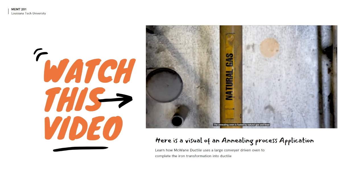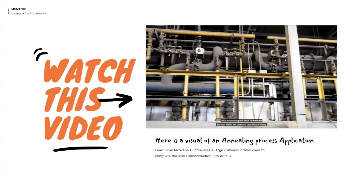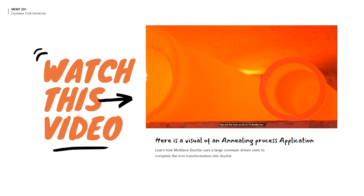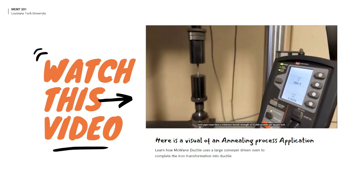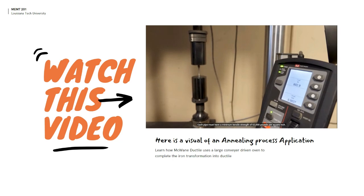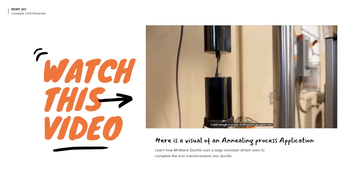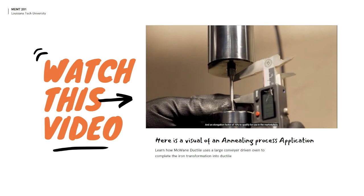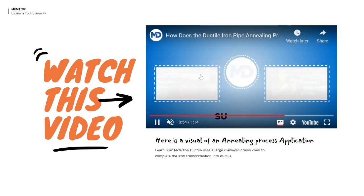The annealing oven is fueled by natural gas and lined with refractory grade brick to maintain the heat within the oven and distribute it evenly. Pipe exit the oven as 60-42-10 ductile iron. Each pipe must have a minimum tensile strength of 62,000 pounds per square inch, a yield strength of at least 42,000 pounds per square inch, and an elongation factor of 10% to qualify for use in the marketplace.